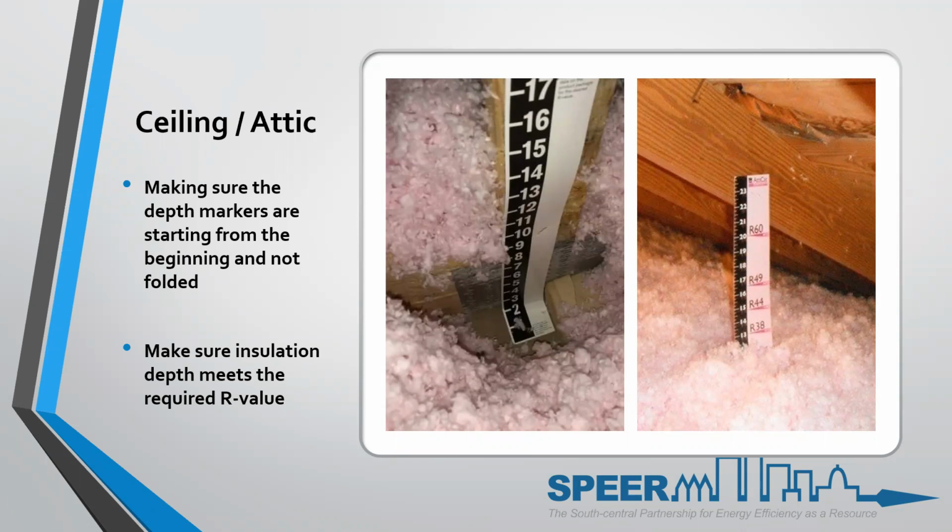This is reading beyond the interpretation of the table. You see the table, you know that it needs to have a full R value of insulation. It needs to be complete and aligned and continuous. And how to do that is things like this, making sure depth markers are installed, which are in a different section of the book. And then make sure that insulation depth meets the requirement of the R value in that climate zone. It was rare for us to see markers installed that way.